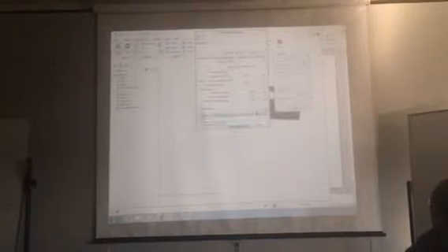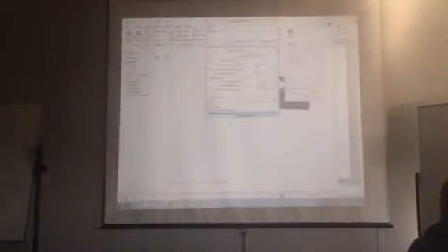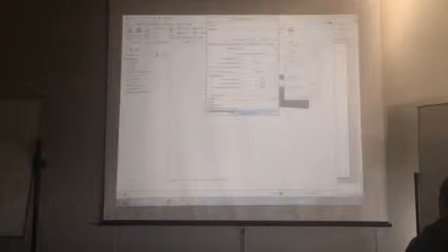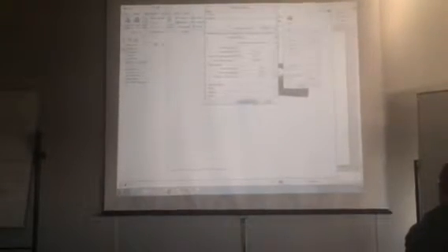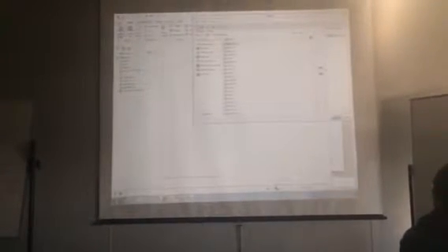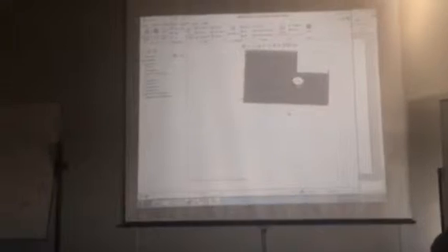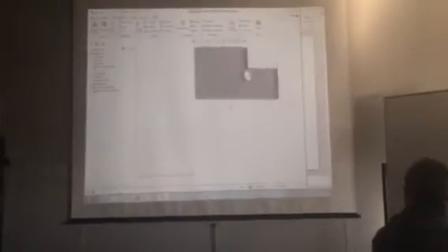You can also put in failure criteria. And you see here we have von Mises and we have maximum shear stress. We also have to modify it more for brittle materials. But I'm not going to put any of those in. So, you see the label now on that. So it now knows its material.